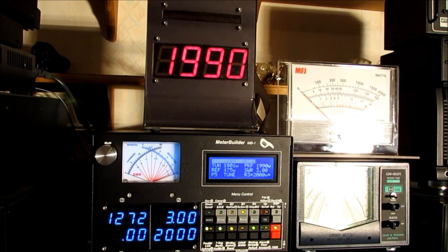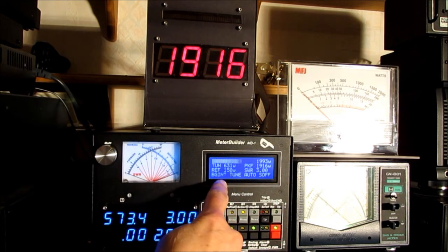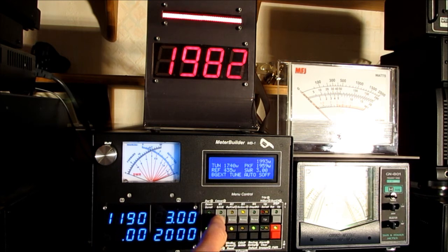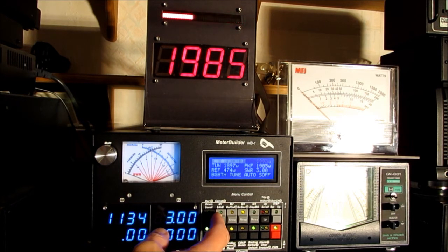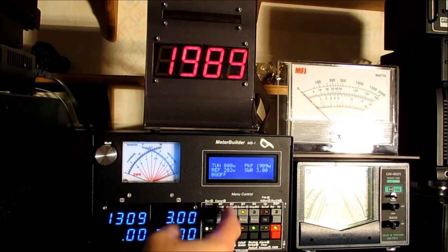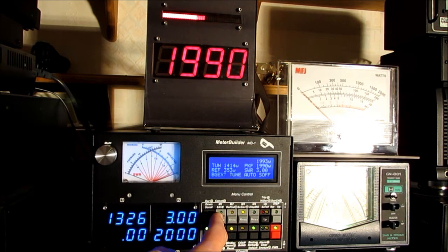Okay, the last menu that we're going to discuss is the bar graph menu. Let me select the bar graph menu with a shortcut button. There are 4 fields. The first field allows me to define which device I want the bar graph information displayed on. The LCD is defined as the internal bar graph display. The LED display, the external LED display, is defined as the external display. I can turn both on. I can turn the bar graph completely off. So let me put both bar graphs on.